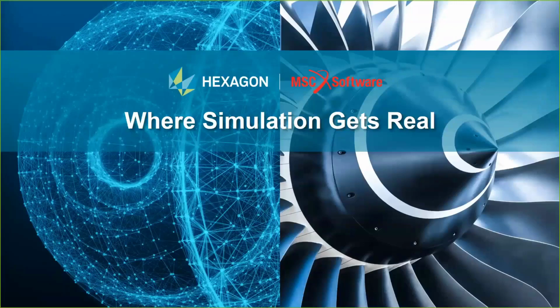Oh, that's a really good question, actually. Yes, you can remesh individual faces of the surfaces that have been created. In my example, I just chose to remesh a lot of stuff, but I could have remeshed an individual face. So that's a really good question. Thank you very much for that question. So you do have local control.